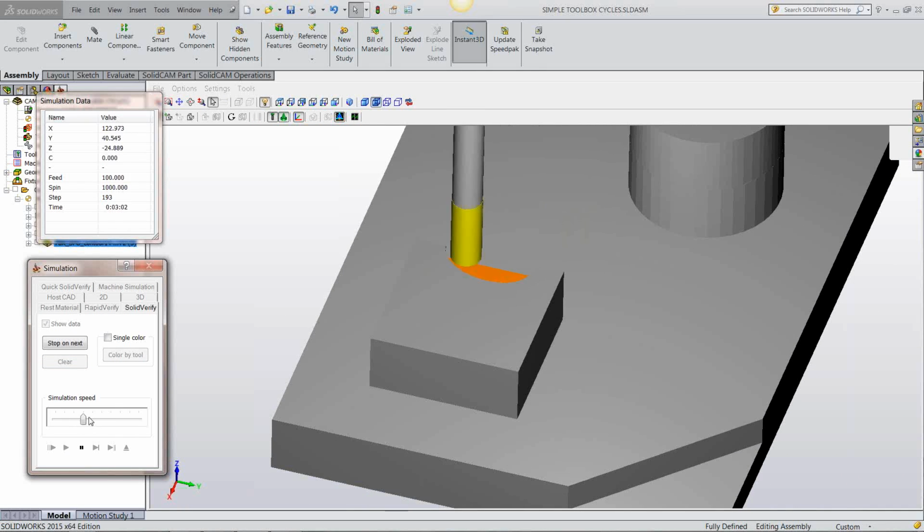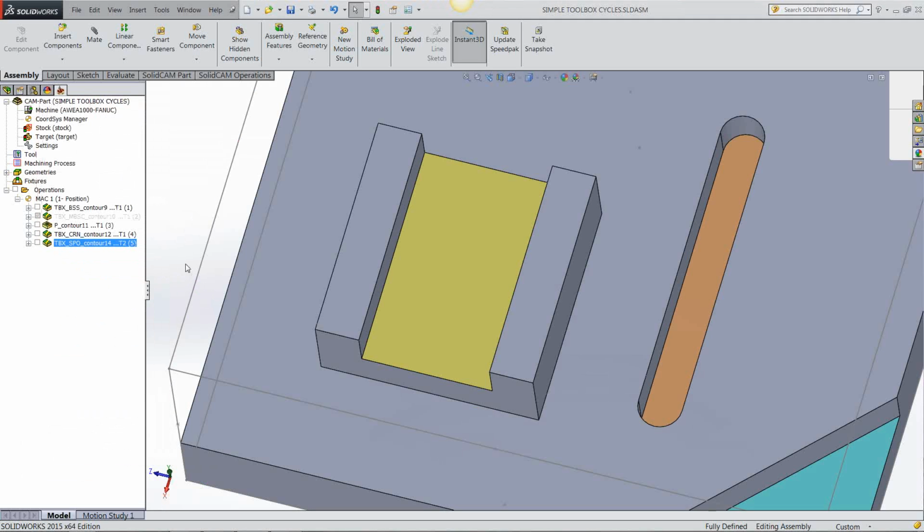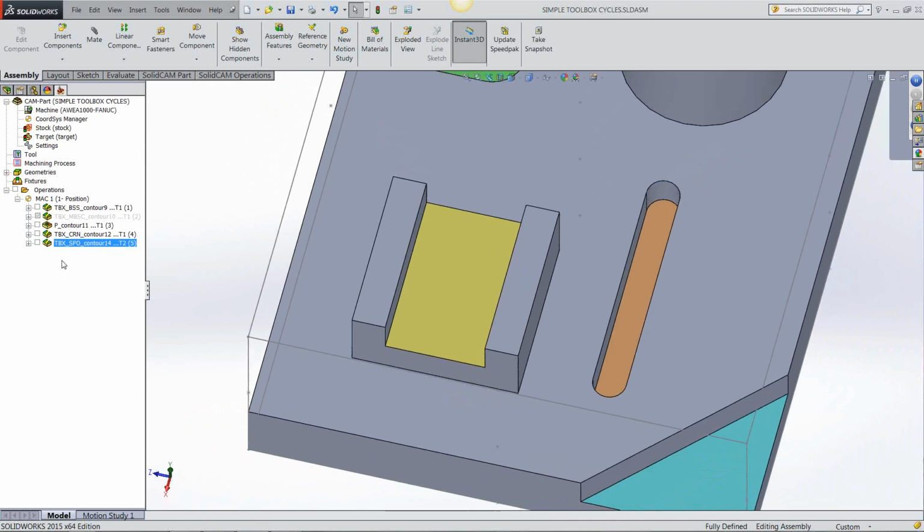Same thing, trochoidal style. Then as it breaks through, it just clears them corners. That was what that little toolpath was that I was saying. And it was too quick for me. I was just going to slow it down and then show you it wiping the sides. Okay, that's that done. Simple slot.